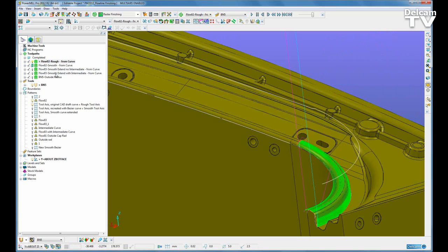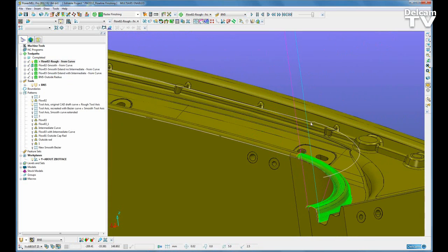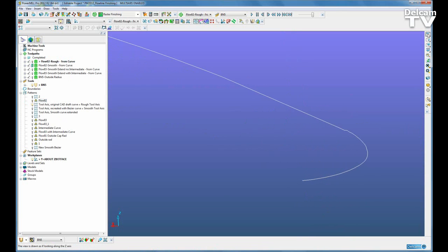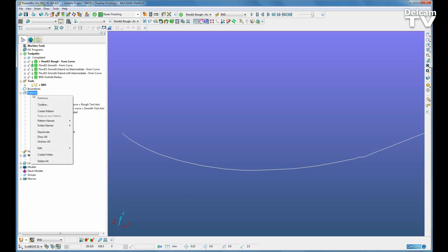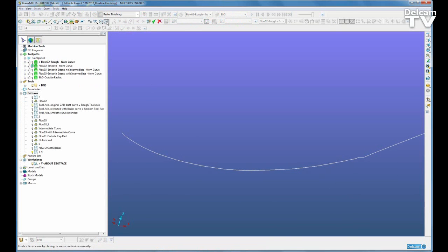What we can do now in PowerMILL is, we've recognised that's a problem, but we've improved the functionality to create a smooth curve. I'll turn off the surfaces. I'll turn off the toolpath. I'll remove the embedded pattern and look at this top one here. Using the Bezier curve, we can simply and easily create a small pattern. Create pattern, go into curve editor, select Bezier.